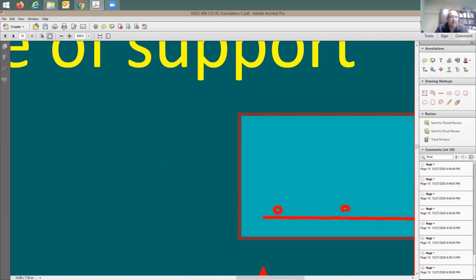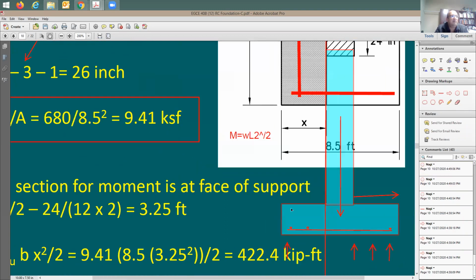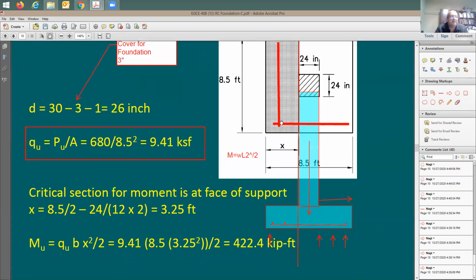Some people would feel that this is just too much, because at the end, I'm going to set this amount of rebar in this direction to be the same as this. I don't want to change it. In construction, you cannot have different reinforcing in both directions for the same footing size. People are going to say, what is going on? It doesn't make sense. So you need to set them equal to each other anyway. So going to an average value in the middle is okay, design-wise.